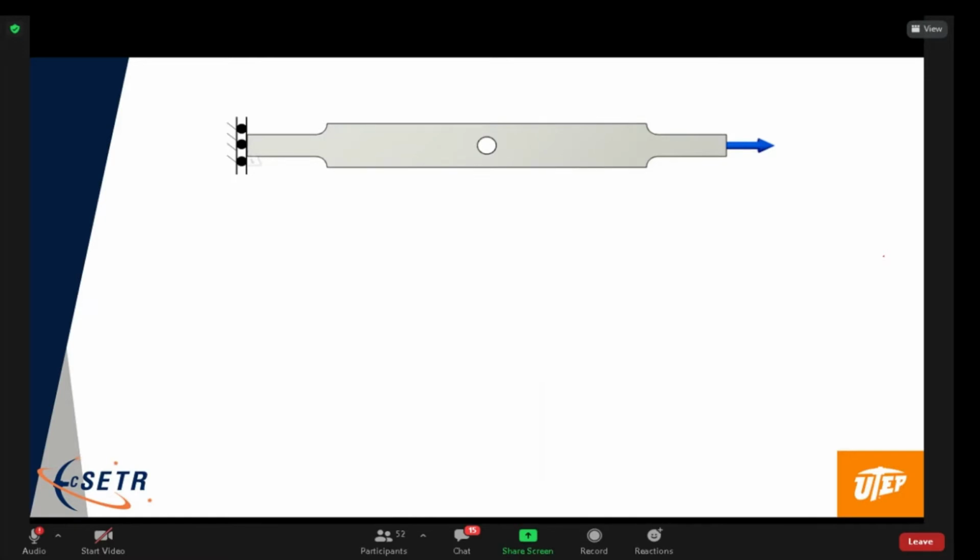So let me just talk a little bit about boundary conditions. Since you've already run these a little bit, you know, when we do finite element models, this idea of picking the boundary conditions really is a big deal, okay? You have to fix every component, so you can't just put a force on the right and left side. It won't allow you to solve that.